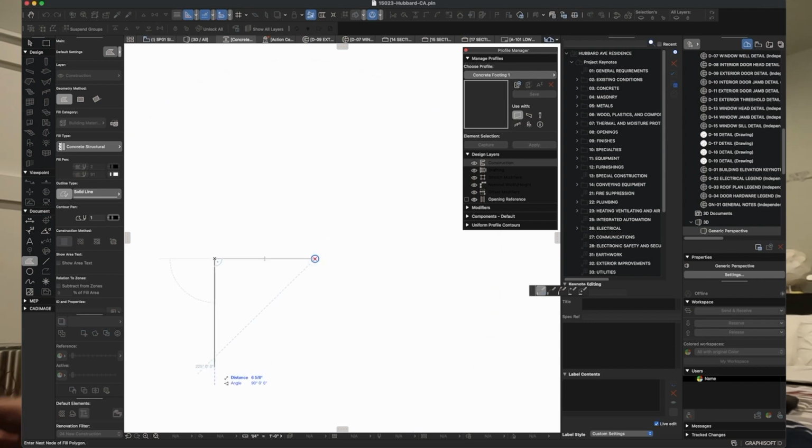And then I'm in a colder climate, so the footings have to actually go further down. Also the soils in my climate tend to be pretty poor. The Great Salt Lake Basin is actually in an area that's known to have high liquefaction danger. So the soils are all very soft and jiggly in an earthquake. So we typically have to put a bit bigger footings than you might see in places like Tennessee or Virginia or California. So in this case, I'm going to go down 1 foot.